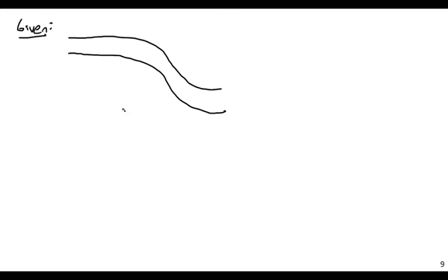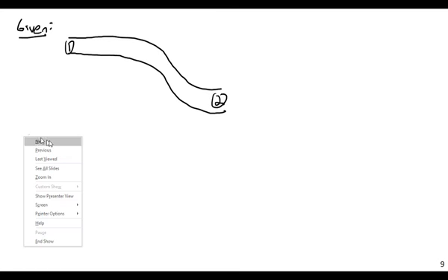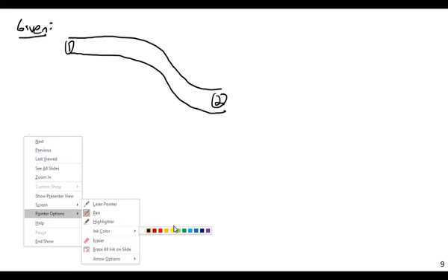This one a fairly straightforward pipe example. Okay, here, let's say I have a pipe that is undergoing a change in elevation and a change in diameter. So let's say I have a big combined system. I'm just going to look at everything. So now nothing will cancel out. Everything's going to be changing. So this is really the hardest case of Bernoulli, at least for the simple Bernoulli that we're working with currently. Okay, so there's going to be a change in diameter. We have points 1 and 2. And then I'm going to have a datum line, which is just my reference line.